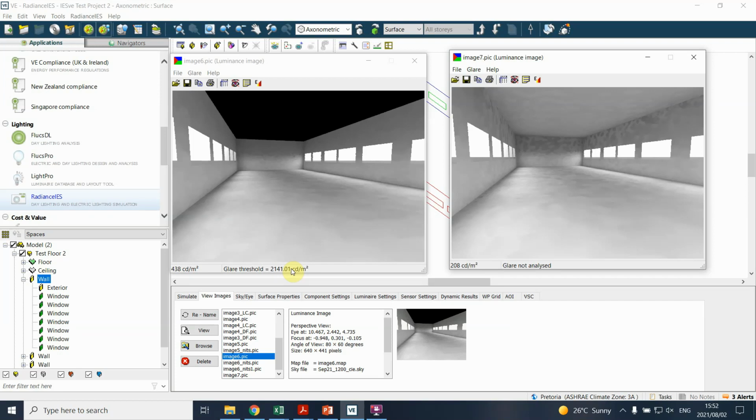There's something called discomfort glare, which often is about reflection on surfaces like computer surfaces. We're not going to be able to assess discomfort glare here. Discomfort glare really is a way to understand that glare is a reflection of light, and so one could rather use a rule of thumb or a design process where you can literally draw the light sources from a space, or you would work from experience there.